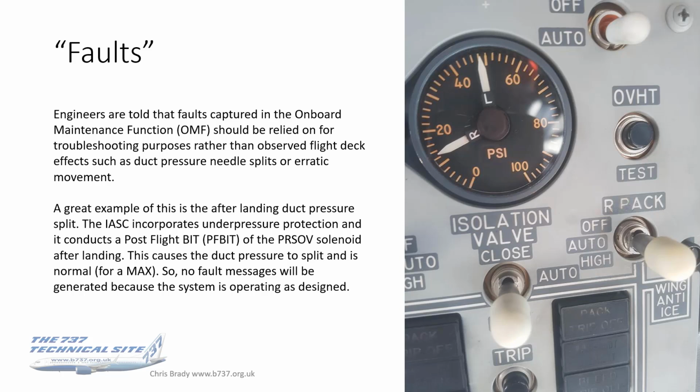They might spot it. So after landing, the ISC incorporates an under pressure protection, and it conducts a post-flight BITE check, called a PF BIT, of the pressure shutoff valve solenoid after landing, and this causes the duct pressure to split, and it's normal for a MAX.